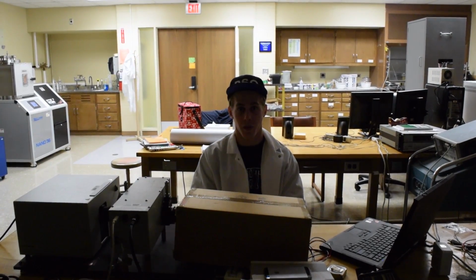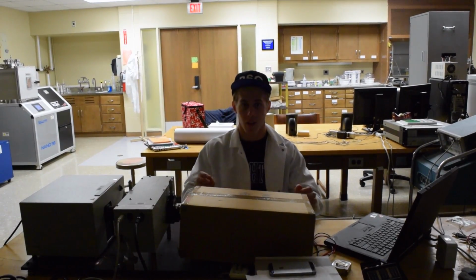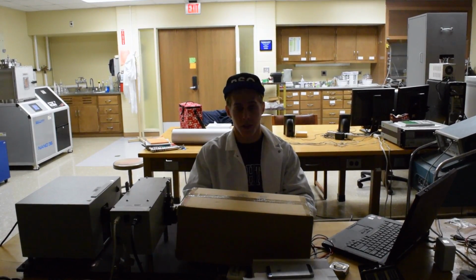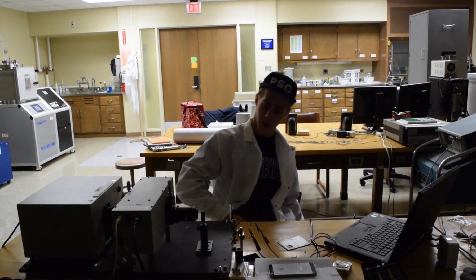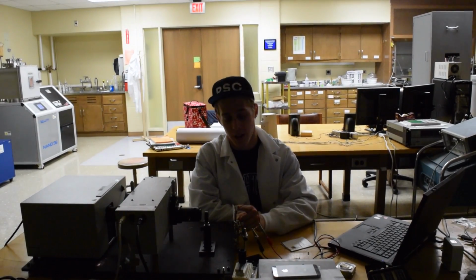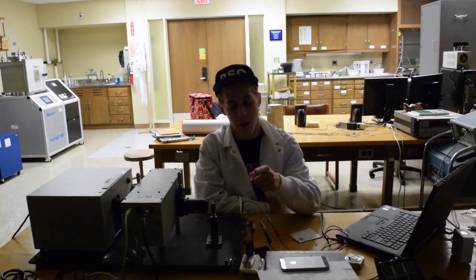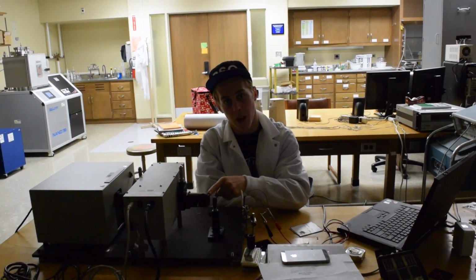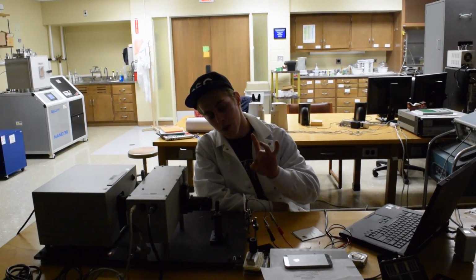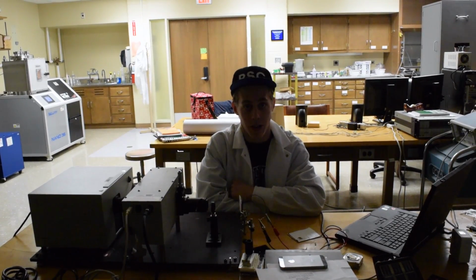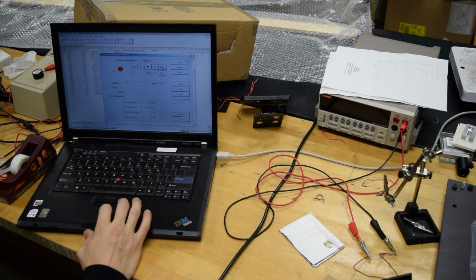Okay, so to review what we've done in order to find the charge carriers leaving the cell. We've built a shade to get rid of some of the ambient lighting in the room, which we'll remove here. We've wired an encapsulated silicon solar cell into our Keithley power meters and mounted it 5 inches away from our light source and covered all of the cell except for a surface area the same size as the power meter we'll use to find our power density. And we'll move into our Cornerstone utility program.